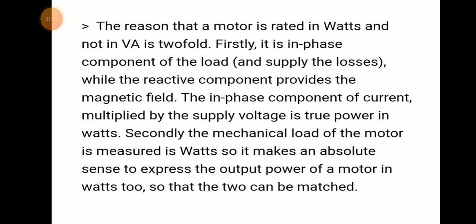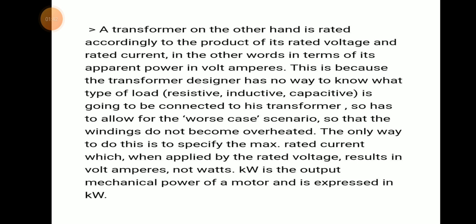To repeat: first, the in-phase component of load current does the work, while the reactive component provides the magnetic field. So the in-phase component multiplied by supply voltage will be true power. Secondly, the mechanical load of a motor, that is the output, is measured in watt. So that makes complete sense, and the two can be matched.